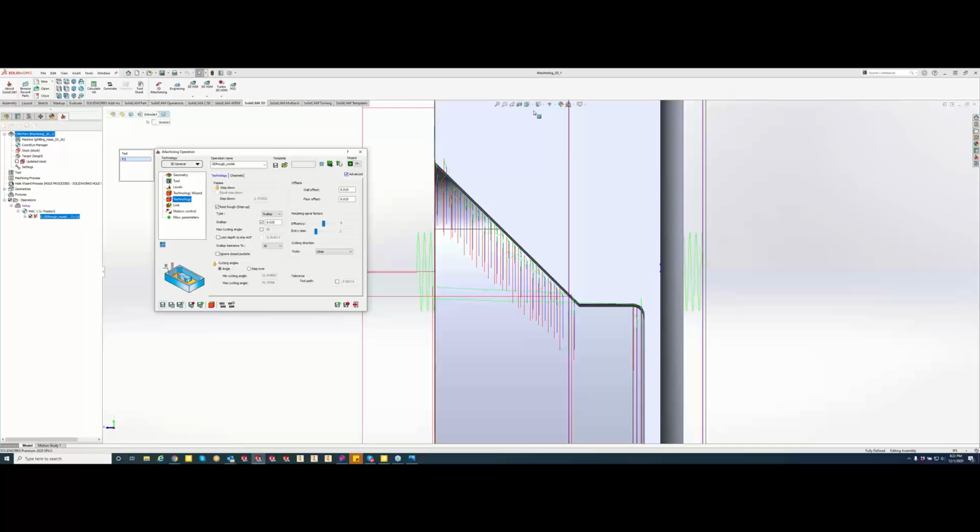It is, to a certain extent. If we want to start in a specific area, what we'd want to do is almost drill out that area or create a little pocket, like a starting platform. Because based off of the algorithm, it's going to try to start from the center and work its way out always. Now, if we start far on the right side and work our way across, we're not getting the most efficient cut that way. And that's why we don't start from the corner. We always want to start from the center.